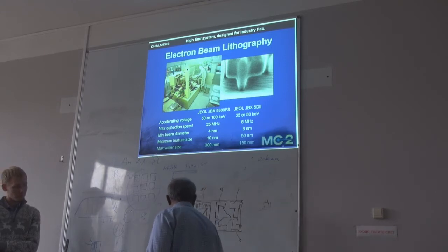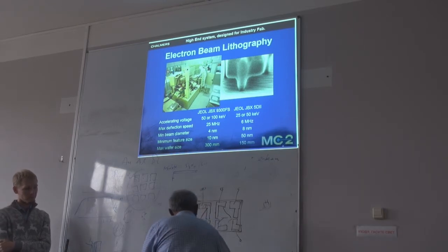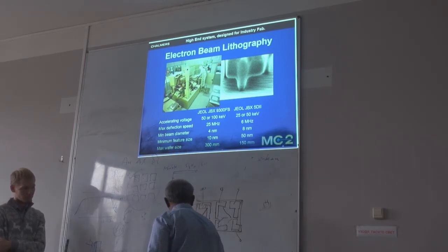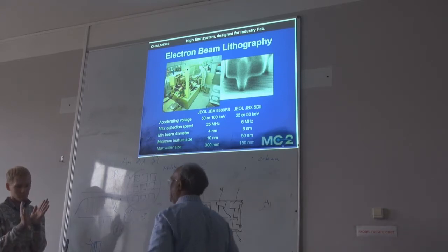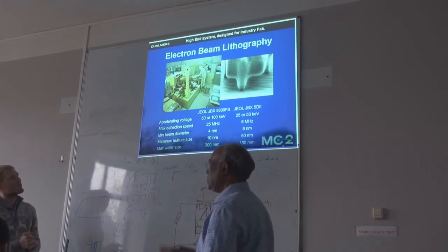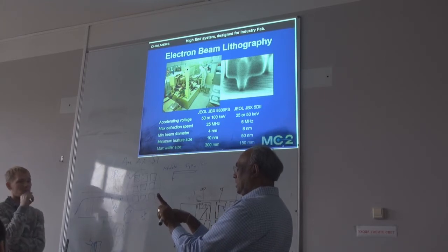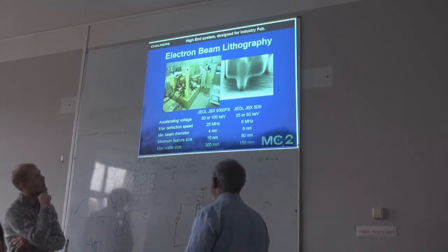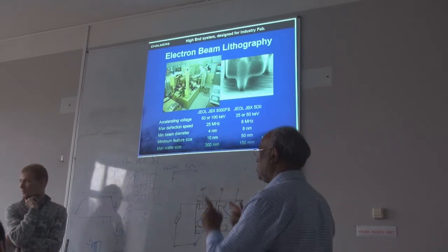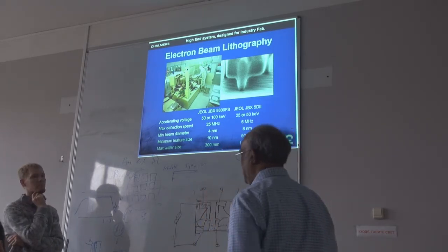But if you do at an angle like this, then you are only exposing this part, right? So then you can do next one from this side, then you can reduce that separation. Okay. So you can have something called the angle deposition. That also we try sometime to make a much narrower separation.